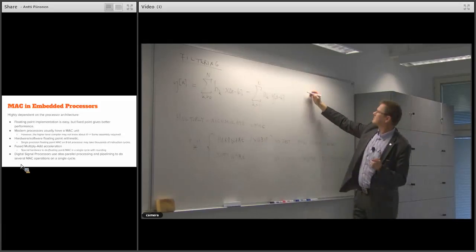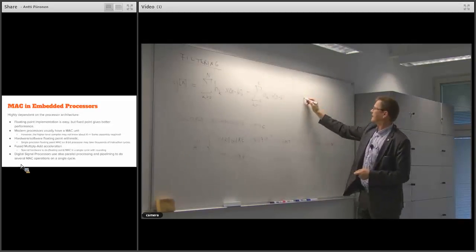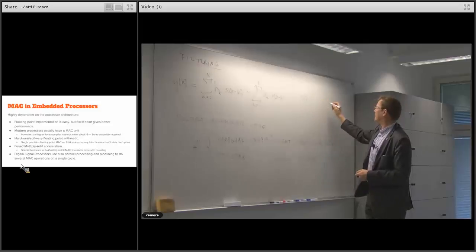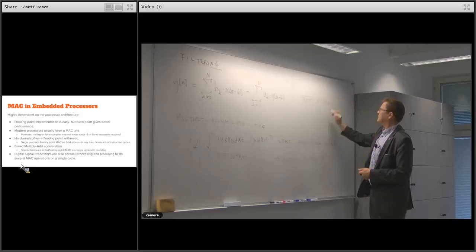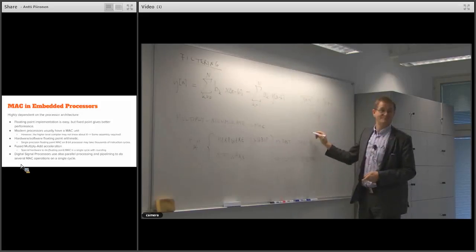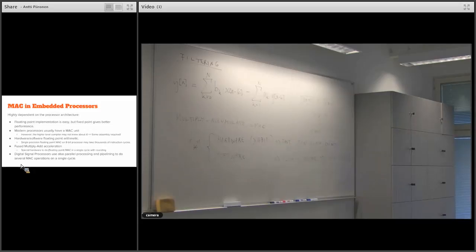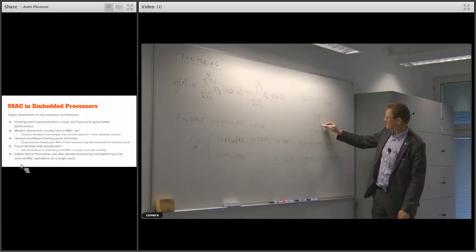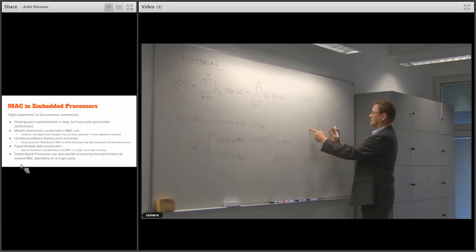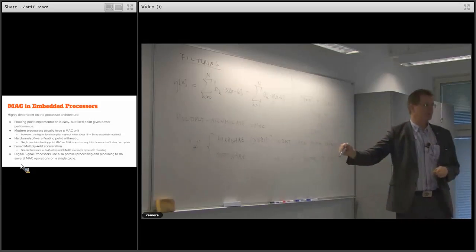With fixed point arithmetic, if you have, for example, 8 bits multiplied by 8 bits, the product is actually 16 bits. You have done multiplication with 8-bit numbers, right? It gives you a 16-bit result. So the question is, how do you take the correct 8 bits, since what you want is the same word length for the output as for input.